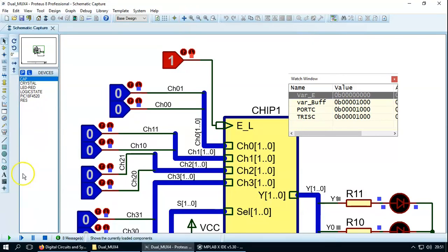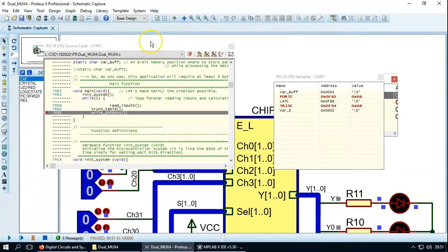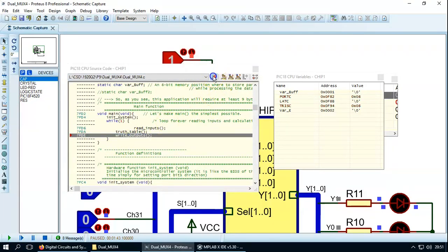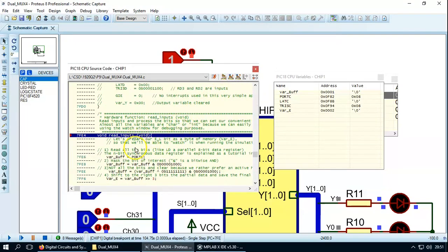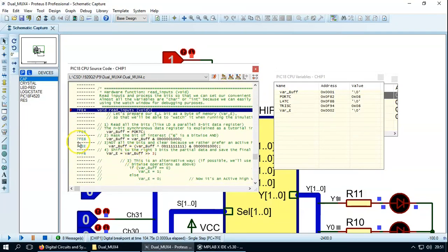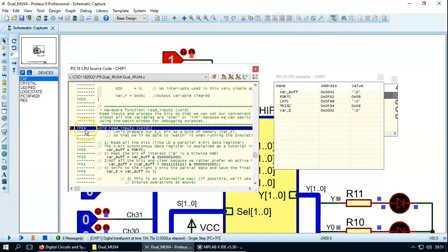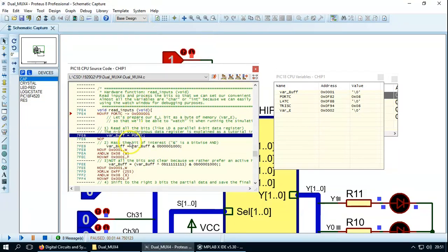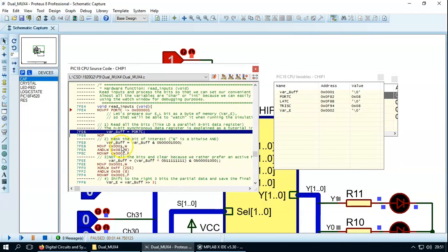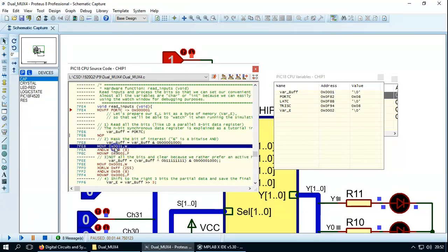That's a good question. To solve that, you have to go step by step. Because the machine you see is running continuously, you may like to go into the read inputs, for example, and place what is called... you see, this is the code that is saved in the ROM program. What you see now is the C, but with a right click anywhere here, you can just disassemble. In this way, you have the code in C and then the real code in assembler that is executed.